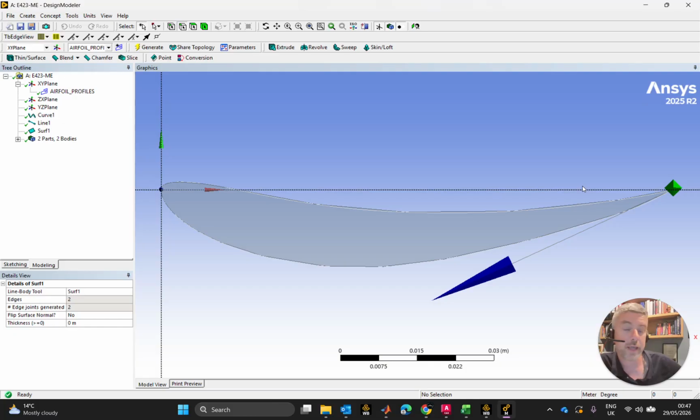Which means that if I am putting an angle of attack in that, that'll more than likely be the trailing edge that'll be up high, which is the edge that's closest to the tire. If we use a Hoosier tire, depending if we're going for a 10-inch or a 13-inch wheel, it will make a difference. But if you're going for a 10-inch, say, just taking the first one that shows up on the website, the trailing edge is just a wee bit above the hub of the wheel, which means there is an awful lot of tire still above the airfoil.